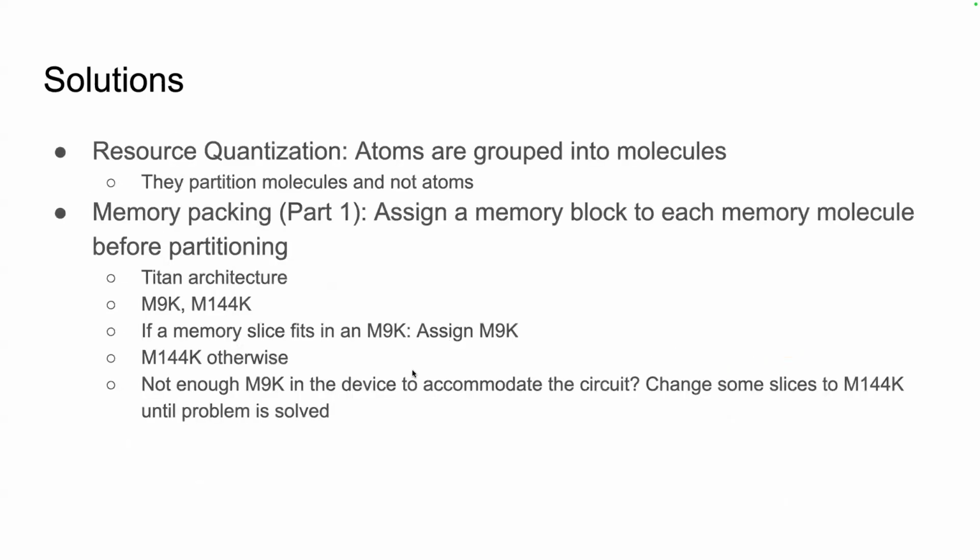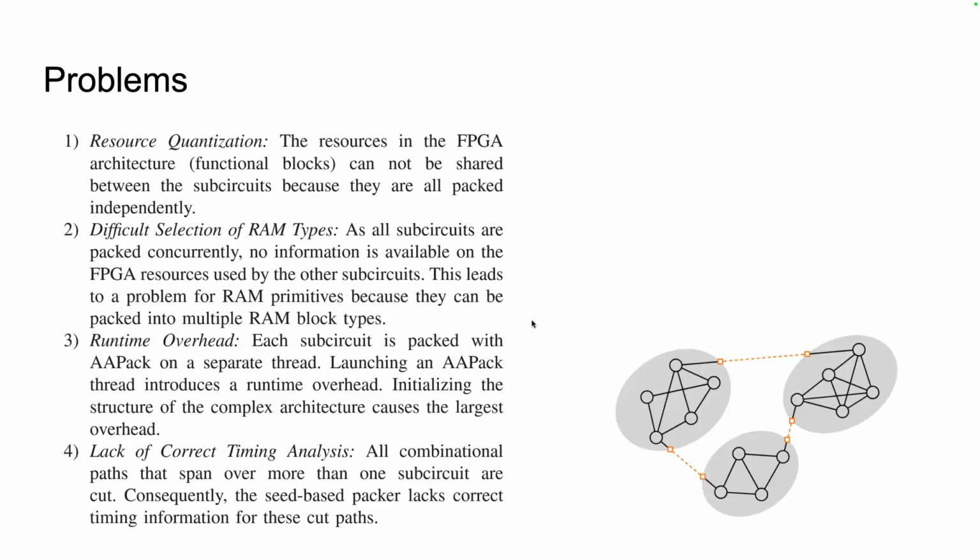Wait, that's so interesting. So they're invoking VPR as an external tool, and then they are basically feeding it a fake netlist for each subcircuit to get a packing. Yes. And there is a way you could put delays on those edges by adding constraints to an SDC file. Do they talk about that? Oh, that is what they do. Okay, perfect. Cool.